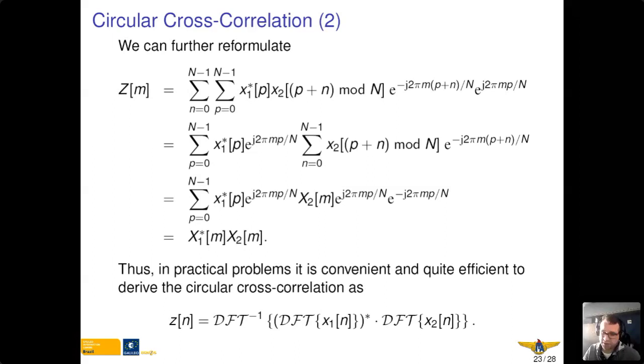And this is sufficient to start the tracking in most cases, in all cases, if we only have the resolution of the sampling. Because usually we have at least 2-3 samples per chip, so we are already in a sub-chip resolution, and this, as you had seen, is needed also for signals with higher order BOC and so on.